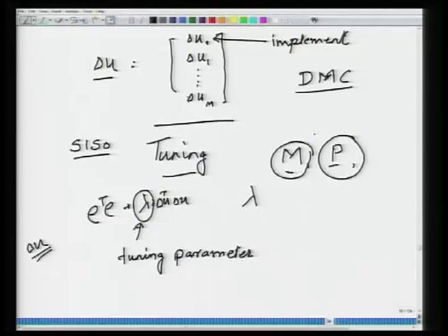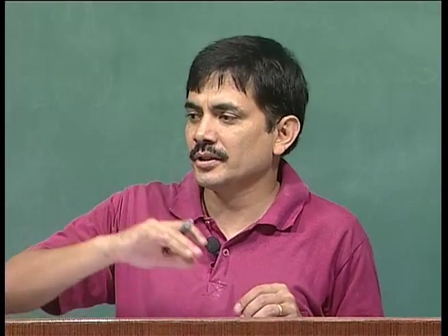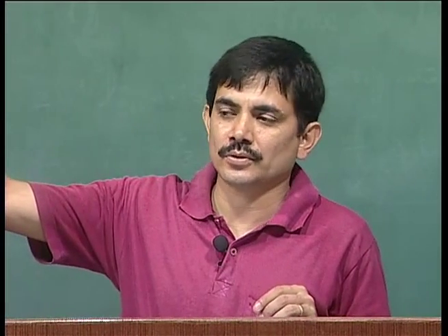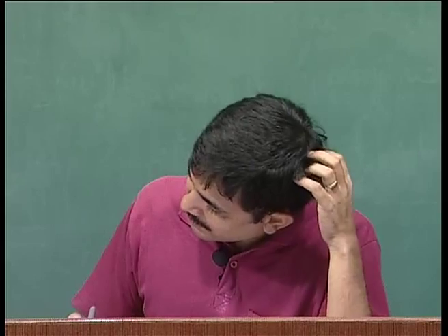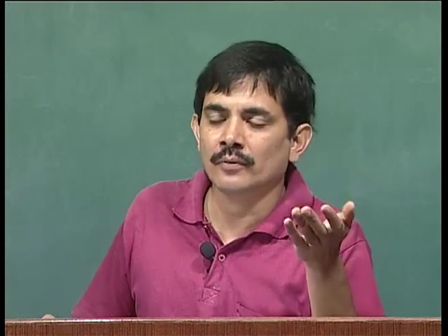Similarly, for the prediction horizon, same thing. Note that P would typically be much larger than M. How much should you predict over? Well, at least one time constant. If the step response takes 30 minutes to line out, you should be making a prediction for at least 10-15 minutes. And M would typically be, say, 1/2 or 1/3 or maybe even 1/5 of P.